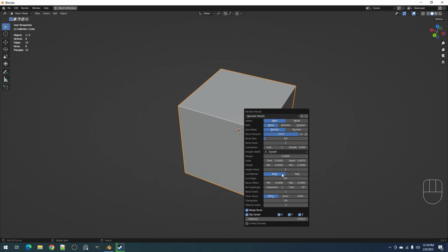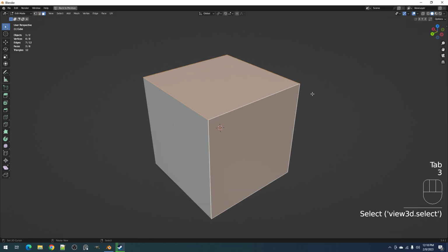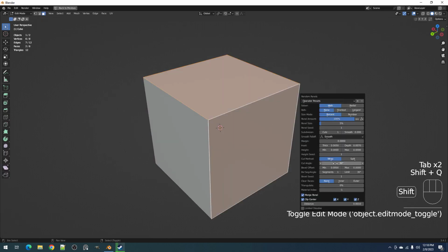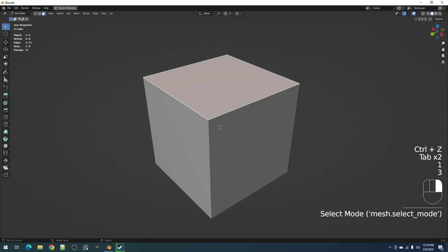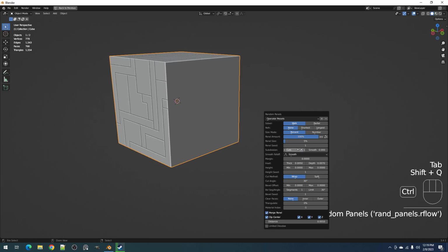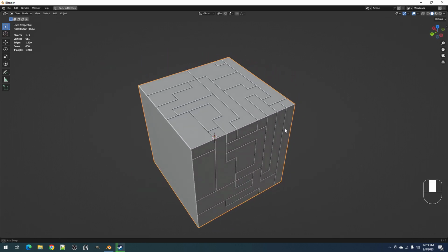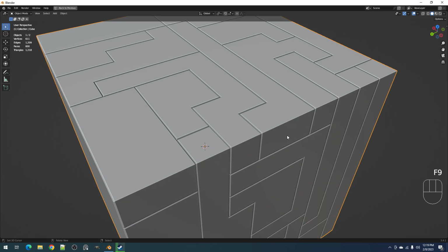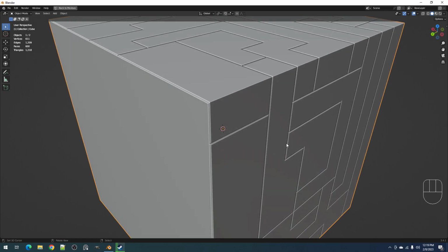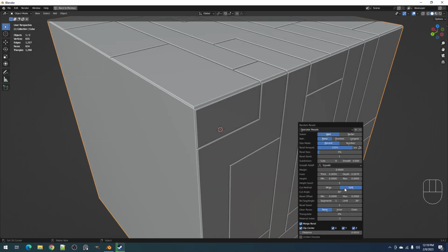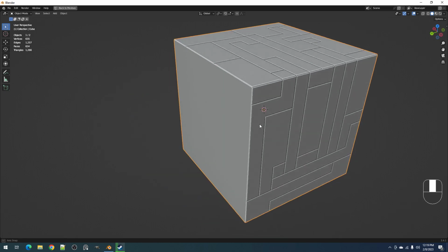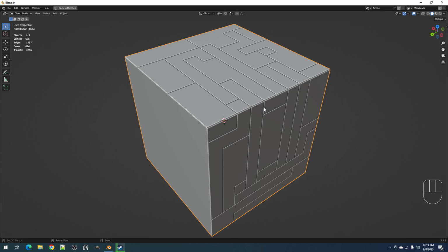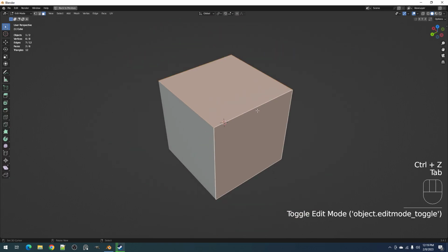So right now the default is wrap, which means that the cut edges, the sharp edges, depending on the sharp edges, the cut angle right here, okay, we'll try to wrap the islands on the sharp edges or hug it, but with split, it'll just split the sharp edges, the angularly sharp edges, not the marked, but also the marked sharp edges.